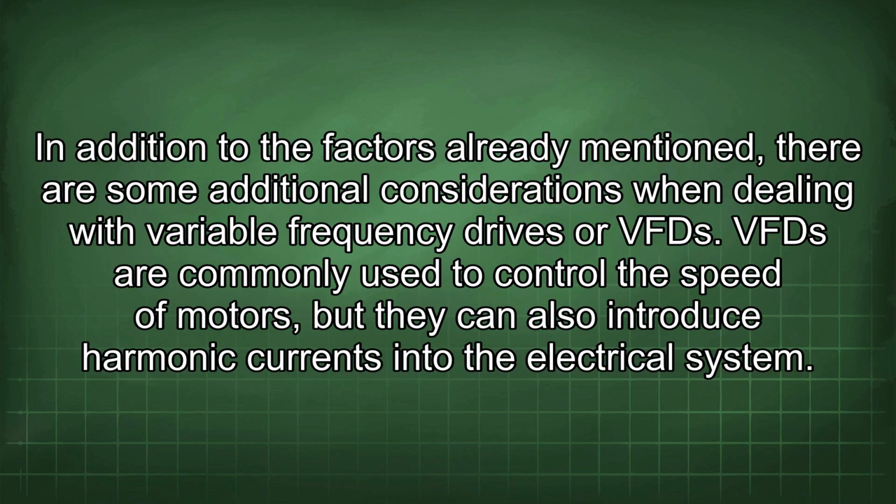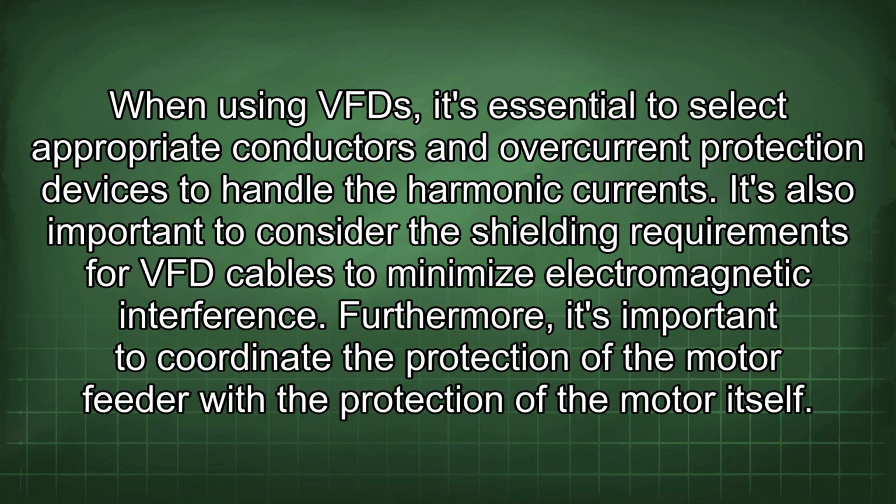In addition to the factors already mentioned, there are some additional considerations when dealing with variable frequency drives, or VFD. VFD are commonly used to control the speed of motors, but they can also introduce harmonic currents into the electrical system. When using VFD, it's essential to select appropriate conductors and overcurrent protection devices to handle the harmonic currents. It's also important to consider the shielding requirements for VFD cables to minimize electromagnetic interference.